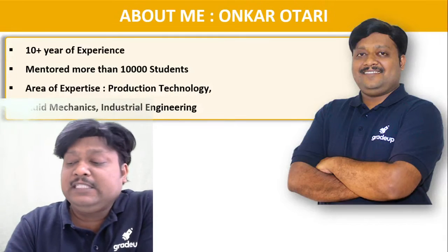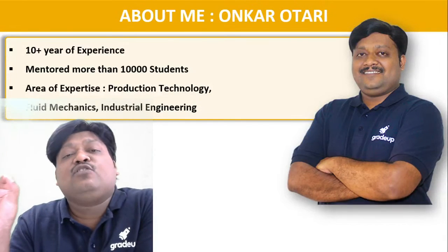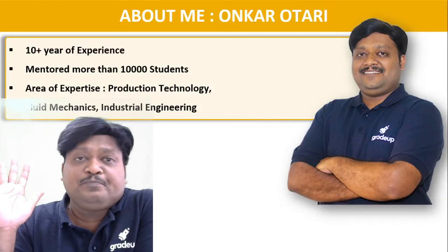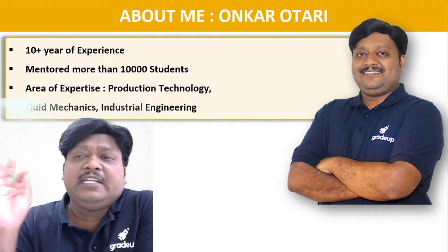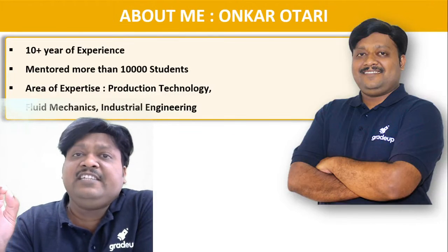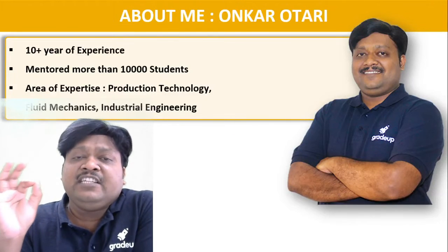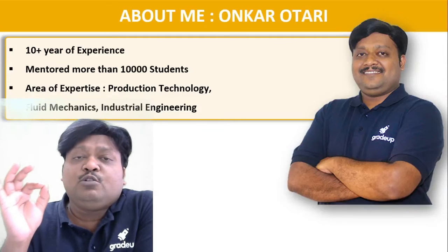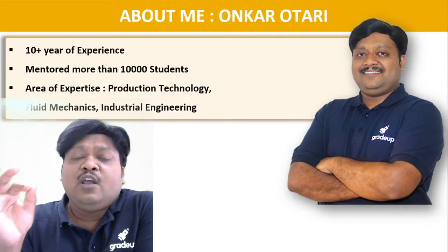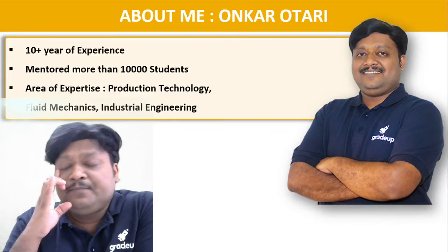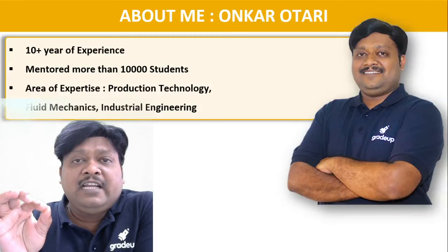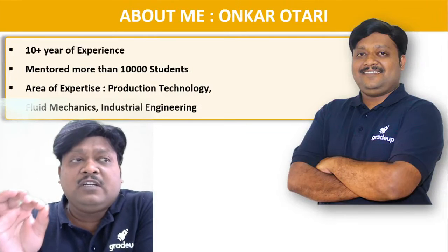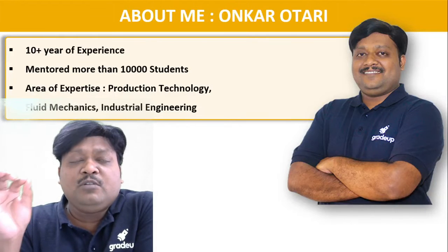So dear students, I hope the fundamentals of metalworking are now clear to you, starting from the simple stress and strain, that is the nominal engineering stress and strain, then the true or instantaneous stress and strain and the relationship between them. Then in the plastic deformation zone, we know which law is valid: the Hollomon equation, sigma t is equal to k into epsilon to the power n.